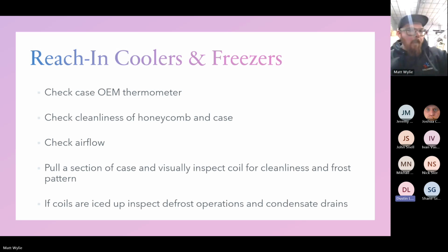And along that, the termination side of it too, when we went to the KE2 factory in Missouri, the guys had said the same thing over and over again regarding defrost. It was like, temp, or what is the ice melts last, right? If you're in a grocery store and it's got an actual temp sensor hooked up to an E2 or a Danfoss controller and it's terminating defrost based off of that temp sensor, obviously your coil temp's going to be different. Is the top colder than the bottom? Is the left colder than the right? Your expansion valve's only on one side.